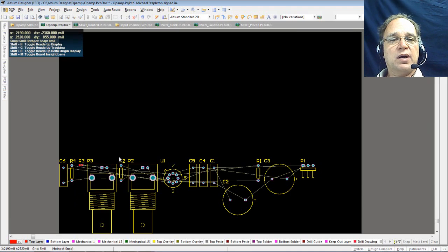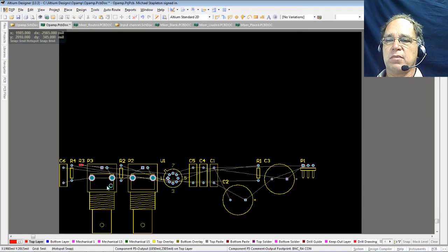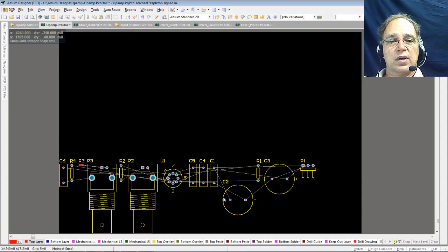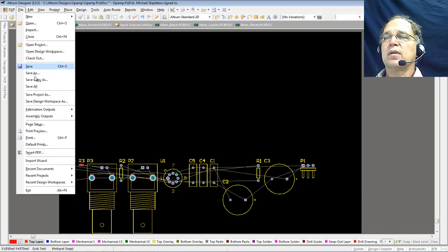We'll have a couple of things we're going to want to do now. I'm looking at my parts here, and I see that I have my B and C connectors. Here's that round can for my op amp, not the footprint I want to use. These capacitors are physically a lot bigger than I need, so let's make some edits and see how we can make those edits. I'll do a save all.